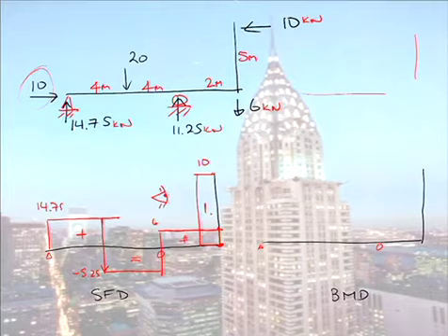Now, as I said, I could just teach someone how to do this and someone would come along and say, I have a positive shear force, that's a downward slope. I have a negative shear force, that's an upward slope. And looking at my bending moment diagram, I know all the slopey directions. My shear force is constant, it's a straight line, so all my bending moments will be linear. So join the dots for me and give me some values.